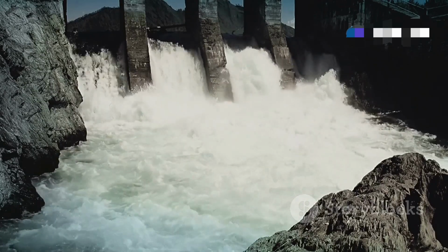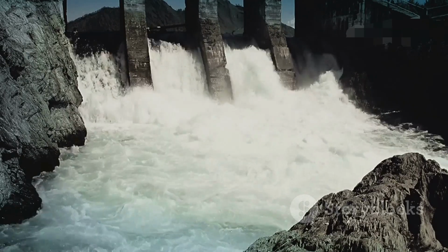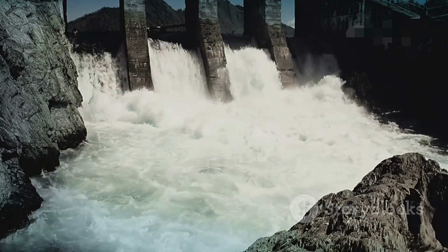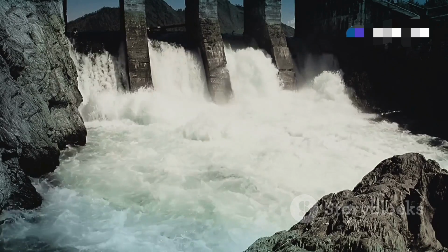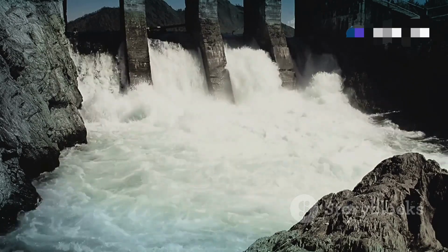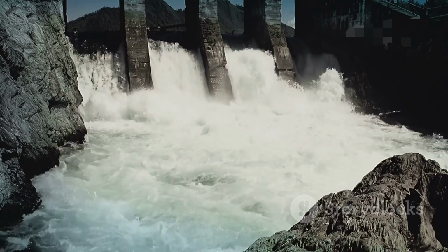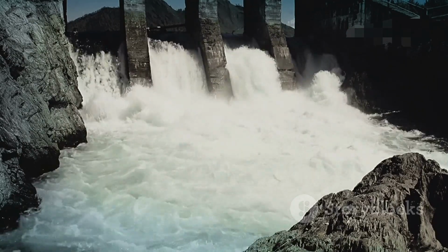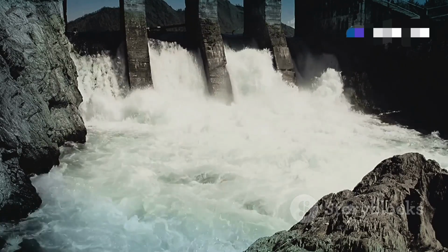The primary dimensions include the final average breach width and the final breach depth. Another important aspect is the slope of the sides of the breach. These dimensions collectively determine the maximum area through which water can flow out of the reservoir. Accurately estimating these dimensions is vital because they directly control the peak discharge of the flood wave. A larger opening will generally result in a higher peak flow and a more rapidly draining reservoir.